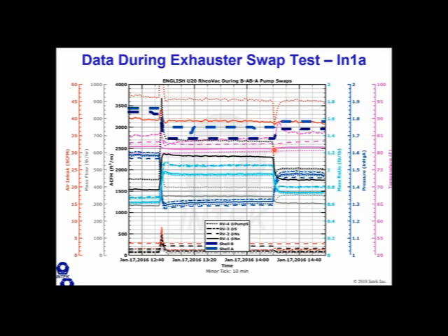And so what we're looking at here is the total flow rate, making sure that the total flow rates look adequate for each pump. So we would expect to see the CFMs from pump B only match or very closely match the flow rate from pump A only. They're close, it's not exact. It looks like pump A is working better. I'm going to go ahead and throw that answer out to you guys already. So vacuum pump A pulls more cubic feet per minute than vacuum pump B. It's not much.